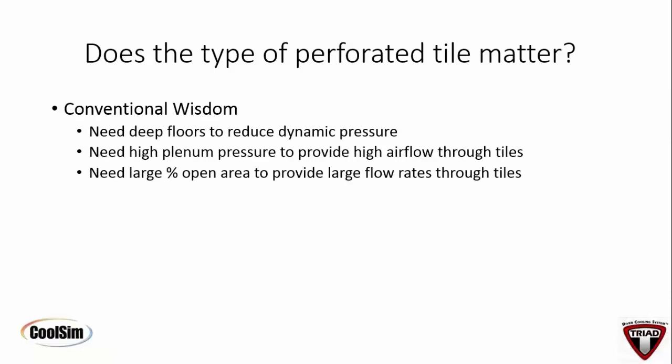So the conventional wisdom, as I mentioned, is to keep the floors deep. The reason this is a popular idea is because there are two components of airflow, dynamic and static pressure. The dynamic pressure is caused by movement of the air. It's momentum related. Typically in raised floor data centers, you have a fairly high component of dynamic pressure because the air is being shot to the center from perimeter downflow cooling units. That's often what I find in data center design. However, air is very lazy and doesn't like to turn a corner to come up out of the floor.